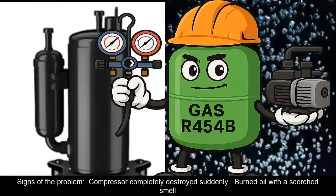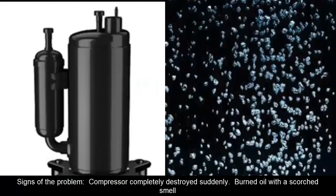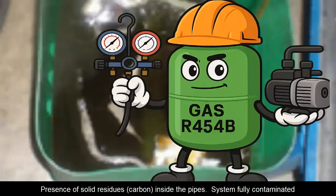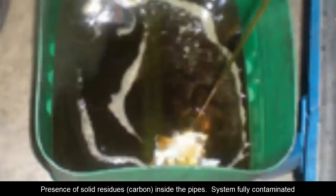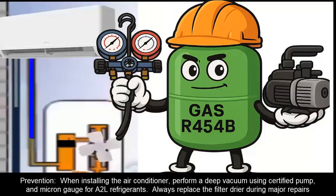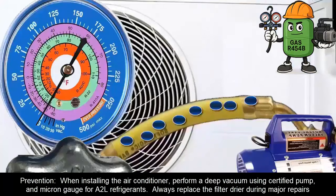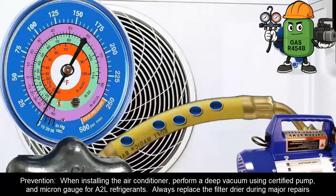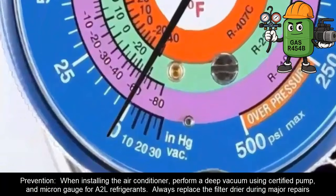Signs of the problem: compressor completely destroyed suddenly, burned oil with a scorched smell, presence of solid residues, carbon, inside the pipes, system fully contaminated. Prevention: when installing the air conditioner, perform a deep vacuum using certified pump and micron gauge for A2L refrigerants. Always replace the filter dryer during major repairs.